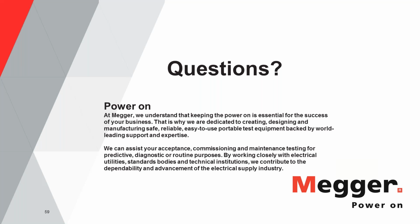In addition to primary injection testing, you should also do a contact resistance test, as Sanket mentioned, to measure the contact resistance, which would in turn tell you the amount of heat losses in the breaker when it's carrying the fault current. And then also the insulation test, to make sure there is a desirable amount of insulation between the poles and from poles to ground.